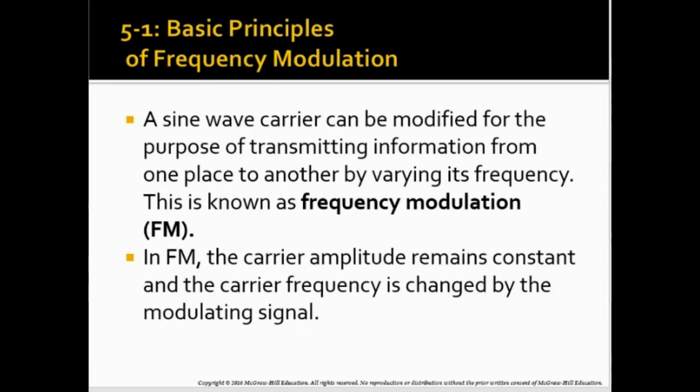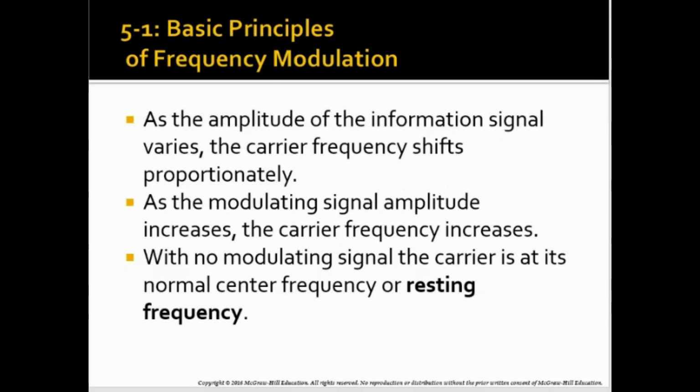So the frequency goes higher and lower, depending on the amplitude of the message. There is no change in the carrier amplitude, it's just constant, but the frequency keeps changing. And that mainly depends on the amplitude of our voice or our message.